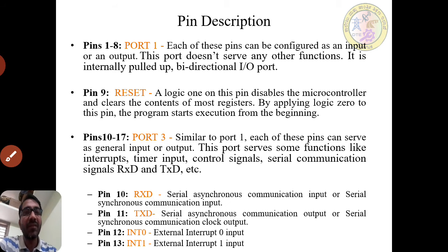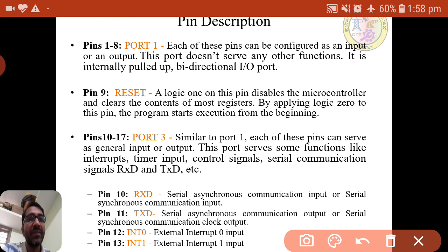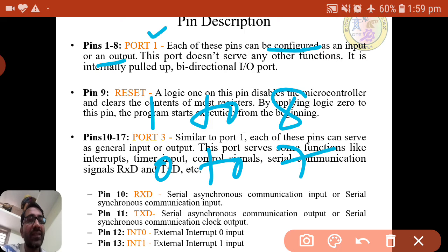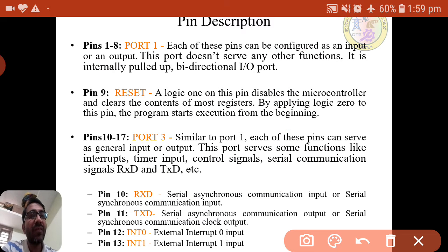Let us start with the first 1 to 8 pins. We call these pins port 1. Port 1 can be configured as input or output. Each of these 8 pins, or we can call them 0 to 7 pins, can be configured as either input or output.